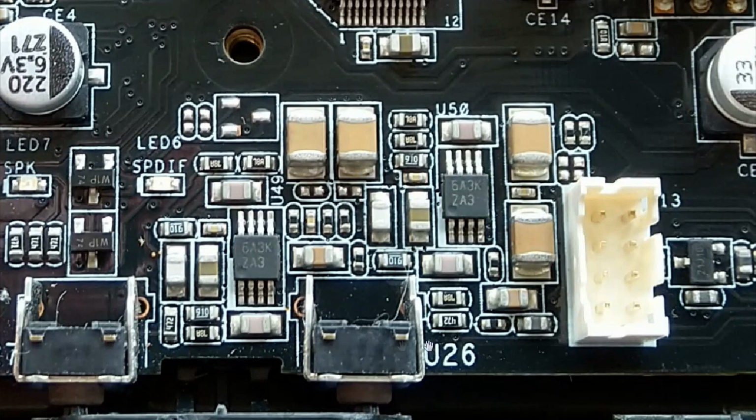The front end we look at here, it looks like they are using ceramic capacitors for coupling, and, well, it's all ceramic capacitors here, right, instead of electrolytic and film capacitors. So I think it's worth trying to bypass this front end and just go directly into the analog to digital converter and see if that improves the performance.